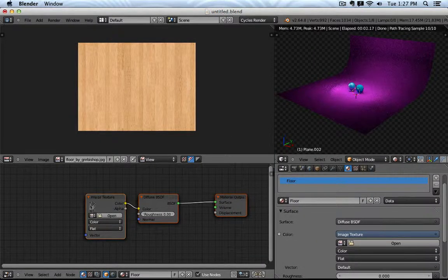And then you see inside the node editor, this image texture got added, and the color from the image texture goes into the color of my material. And currently this is now magenta because we don't have any image yet added. So either here or here, you see the things are the same. I can click on image and, for example, select the wood floor.